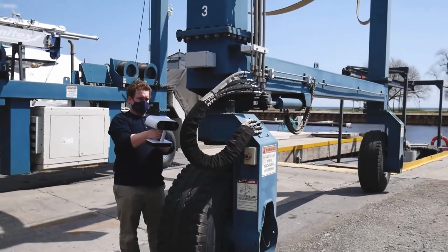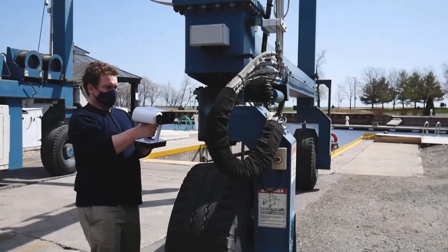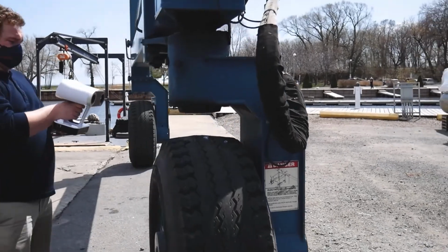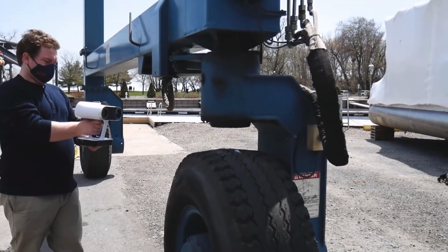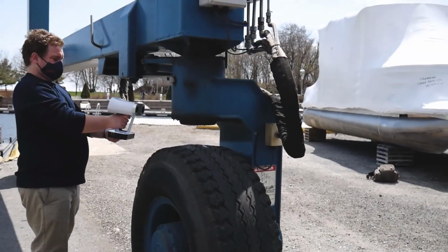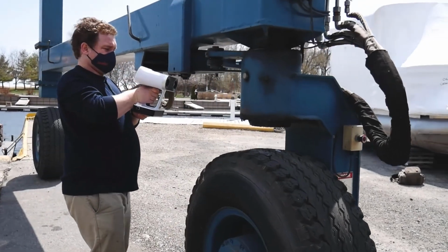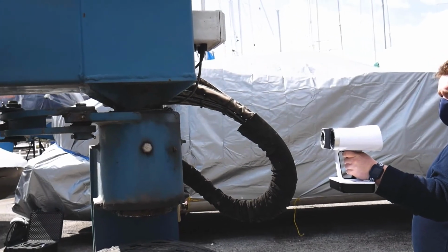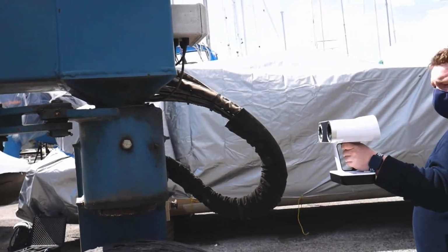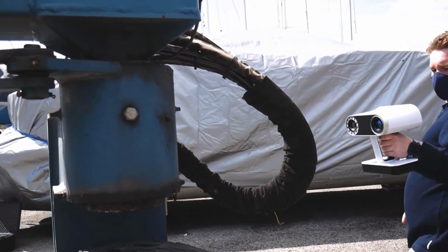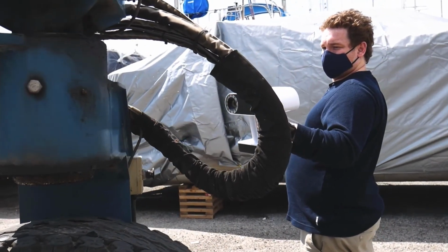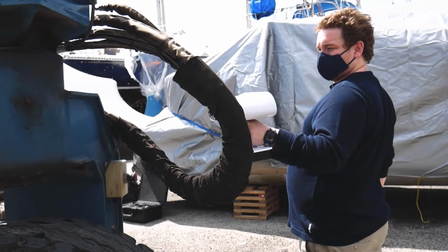I'm looking at the back of the Leo while scanning to visualize what's being captured. The screen on the back shows both the range of the objects being captured as well as the data density or data quality of what you're capturing. Based on the frame rate of the camera that this is recorded on, you're occasionally able to see flashes from the Leo. This is also shown as bright spots on the actual travel lift. This allows you to get a sense of what's being captured in every frame.